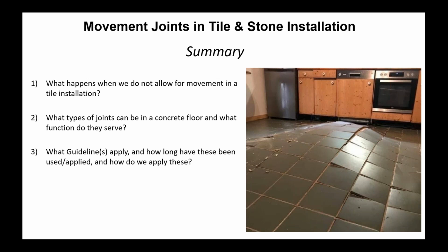What we don't show is the danger that really can occur. I had a good specifier friend of mine in Colorado Springs, and they put in a not a thin brick, but not a complete depth brick. I think it was 3/4 of an inch on the outside of the Colorado Springs City Hall, in front of a parking garage. And he said they were standing there one day and it popped because they didn't have enough movement joints in it, and it went 8 feet in the air. So it blew out a large area. You don't need somebody standing over that in front of the city hall and something like that occurring.